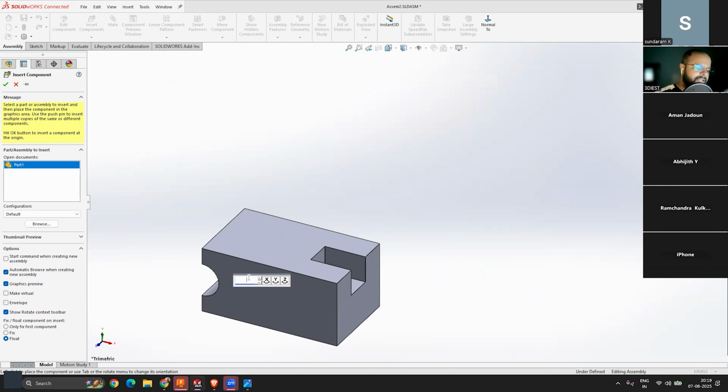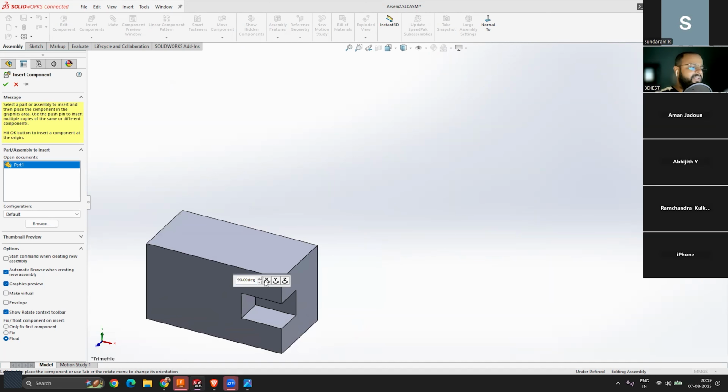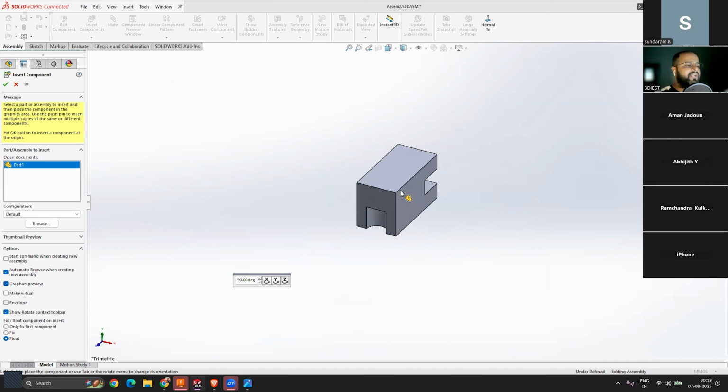or even I can change the angle to change the rotation. Like let's say I want to rotate at 0 degree. So I can rotate it accordingly, not 0, let's make it 180. So if I make it 180 here, and if I rotate it, it will directly rotate 180 degrees. There you can see. So we'll keep the default over here as 90. So we can see the rotations, right? So this way you can rotate your part.